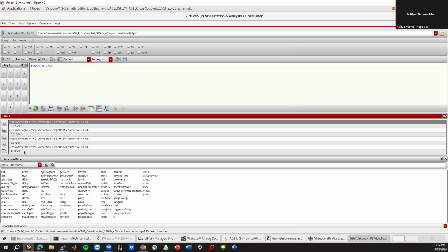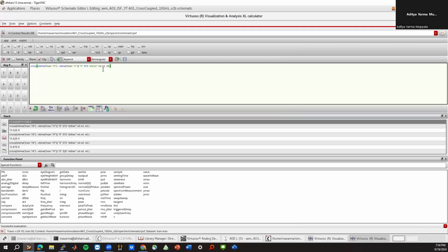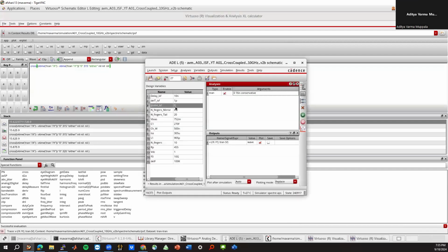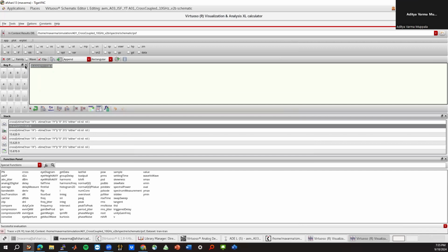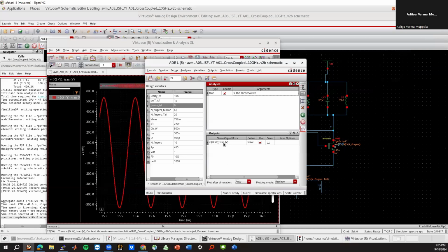Now the difficulty is when you send this expression, if I want to save it, we need to change this from 0 to 1 micro and then sweep delta t, or delay. We need to sweep the delay. So it becomes a little bit tricky. So instead what I would do is just save this numeric value. So I'll press Control C, and I will